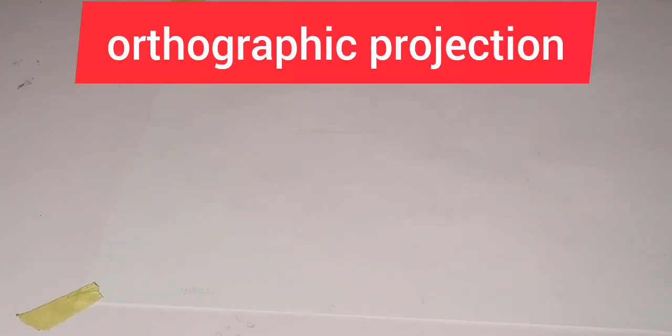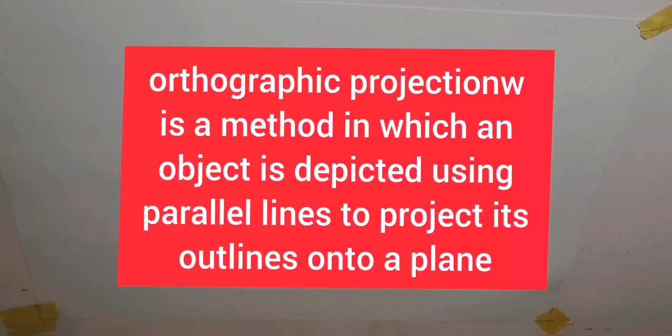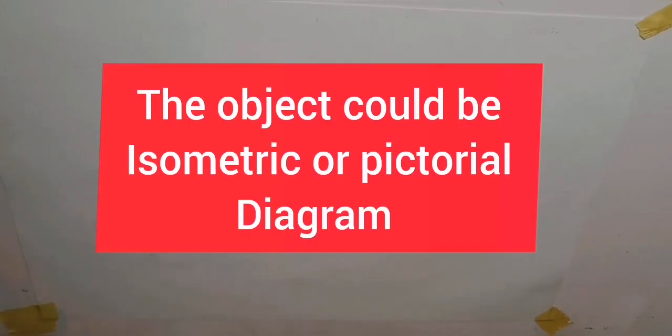Today I'll be talking about orthographic projection. So, what's orthographic projection? Orthographic projection is a method in which an object is depicted using parallel lines to project its outline onto a plane. Like, for example, the object might be an isometric, a pictorial diagram.